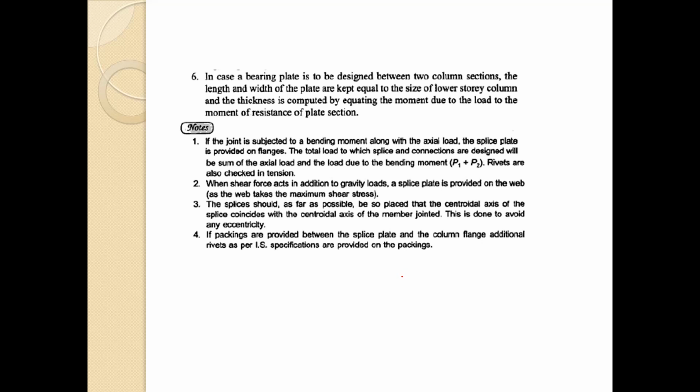If packings are provided between the splice plate and the column flange, additional rivets as per IS specifications are provided. The specification has been given for the packing in IS 800 that we need to check, and additional rivets have to be provided for the packing.